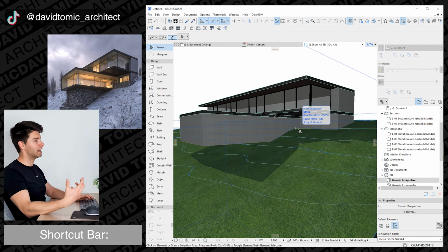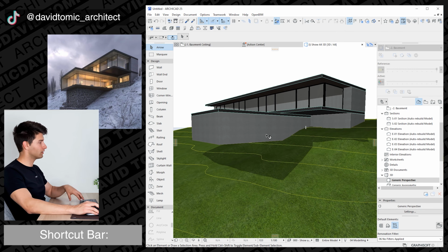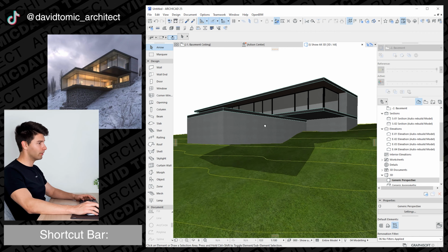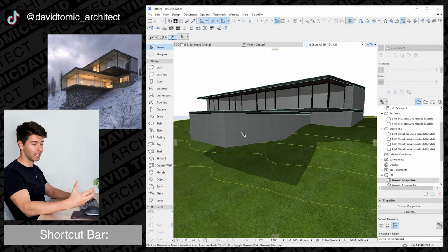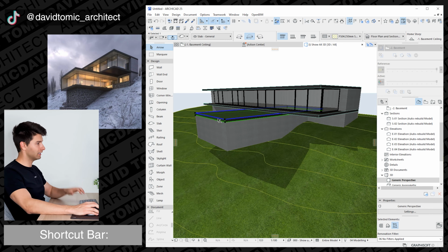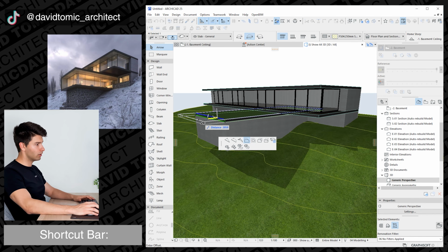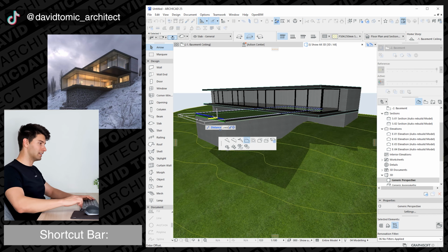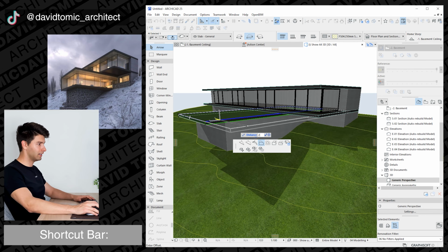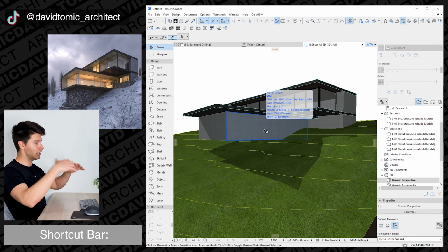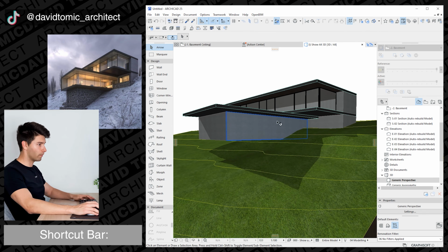Now, we'll point out that the story settings aren't 100% correct in this situation. We really would have to go into it a little bit deeper, but the fundamental basics are there to understand what we're trying to create. Now, we'll also note that the basement ceiling does extend 2 meters. So just like we did a second ago, we're going to click on that blue line and extend it 2 meters here, extend that 2 meters there. So we're starting to get that foundation of this building stacked on top of another building.